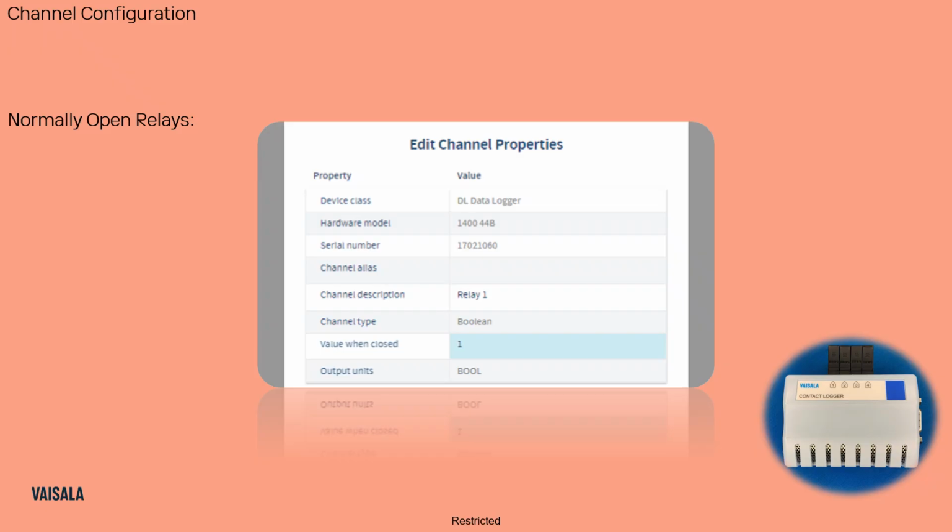And for normally open relays, this is how you're going to set up the channel properties. You're going to give the channel a name. On here it says relay 1, but the way that you set up the value on here for what the Boolean state is under normal conditions. The 0 Boolean is going to be the value when the circuit is open. And 1 is going to be the value when the circuit is closed.